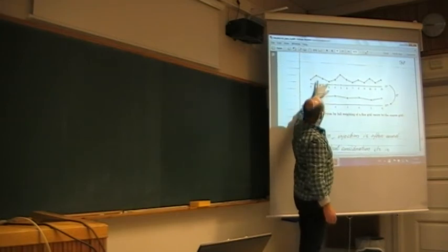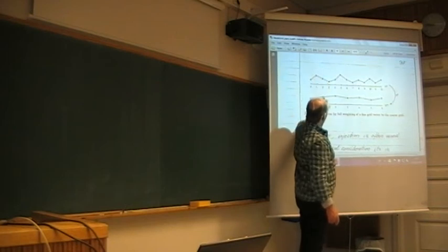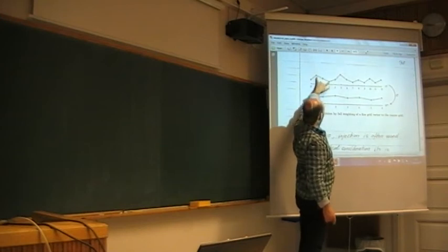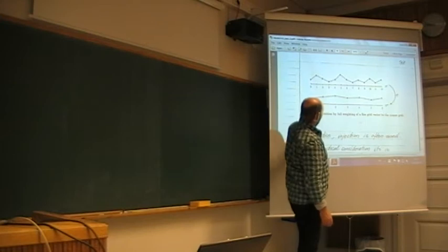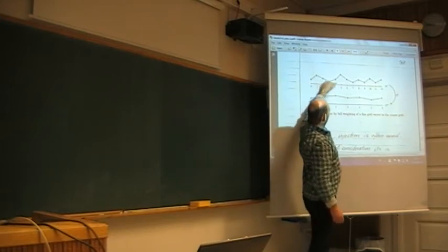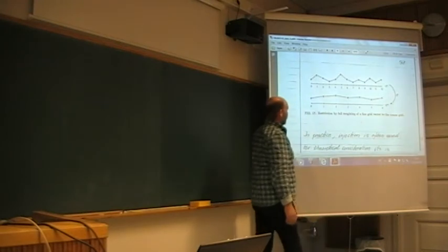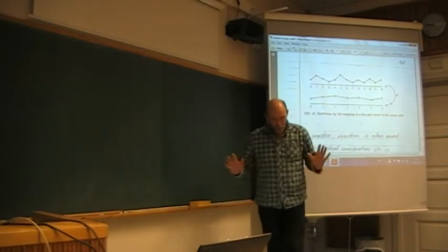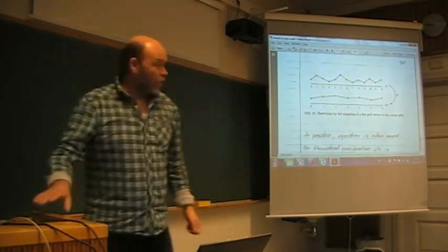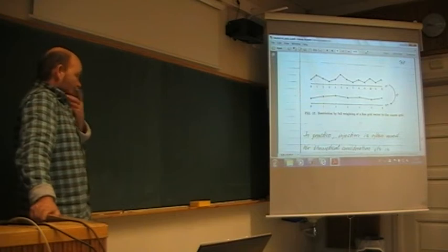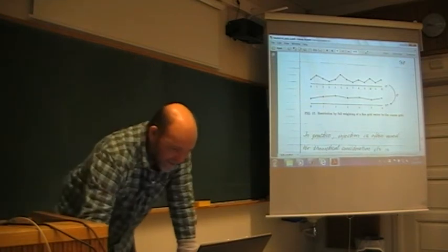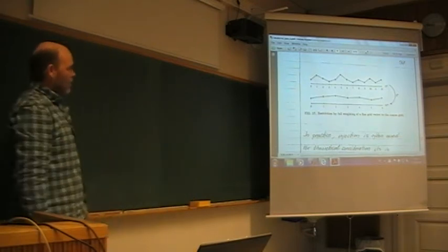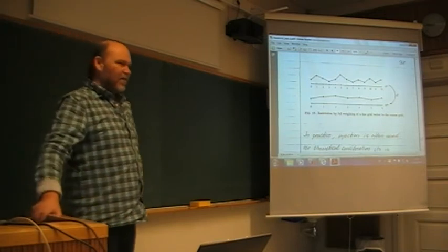If you weight them, you take all these 3 to produce a value here, and the weight is double for the center and 1 on the neighbors. So with the weighting, you will actually smooth the signal a lot more than if you just took every other point. Normally you just take every other point, but again, you have to be careful that the original signal is quite smooth. I would say the signal we have on top there is not that smooth.